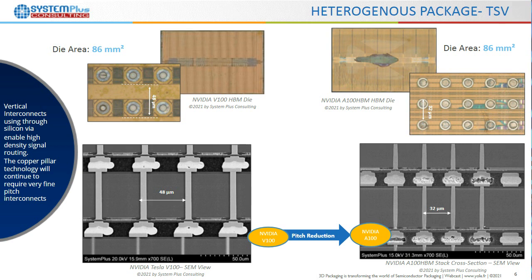Fine pitch is required. As the packaging technology advances, the TSV pitch reduces. As you stack more and more dies, you need faster speed, and this speed is becoming more important. So more TSVs are actually used that result in smaller pitch on the component, which in turn affects the TSV aspect ratio. TSV thickness is reduced, and the etching could become a concern.